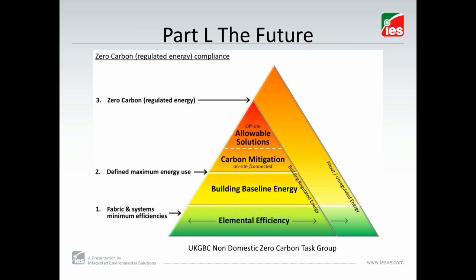So also we've got the Energy Performance of Buildings Directive, as I say, requiring near zero carbon or near zero energy from 2020, and it's 2018 for public buildings. The building regs is considered a successful mechanism for reducing carbon. The UK GBC report states that DECC estimate that together Part L 2002 and 2006 saved 8.3 terawatt hours and 1.9 megatons of carbon by 2010, which was nearly a quarter of total savings from all energy efficiency improvement programmes and policies in the public and private sector.